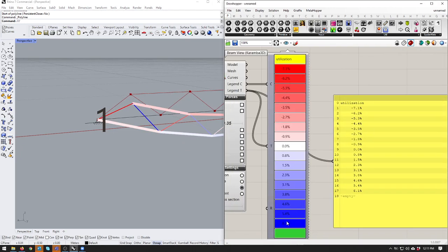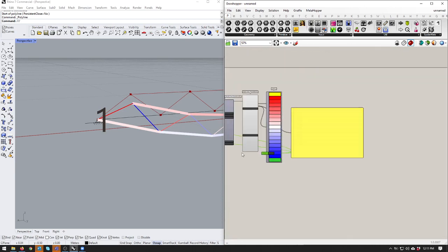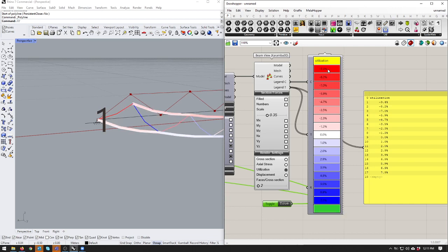to the utilization, we've got 7% and 6%. If I make these pin joints rigid, then the structure ends up using almost double. The structure's far less efficient with all of these being rigid versus all of these being pin. You can see 6.1, 7.1 versus 9, not double, but 50% worse. Do you guys see that?